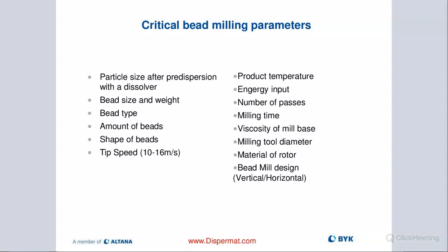Type of material is critical. Ceramic is very popular. The reason is it's very hard and also very resistant to abrasion. Stainless steel on a standard configuration will wear over time, so you'll end up with the metal bleeding into your slurry.